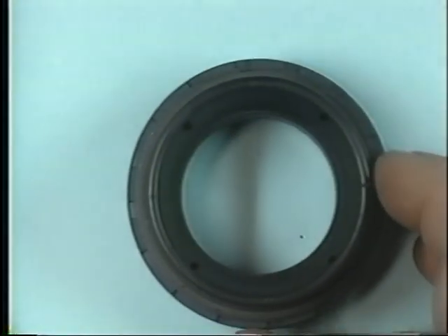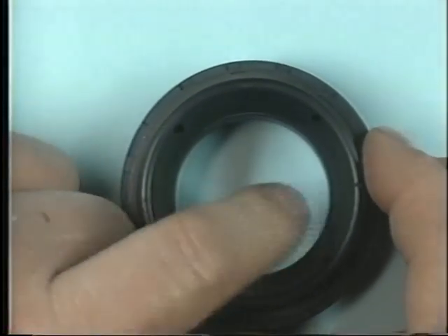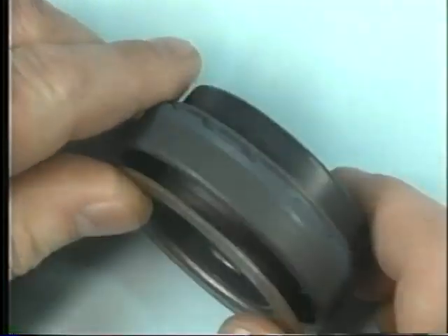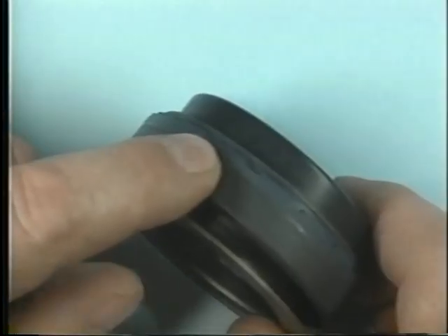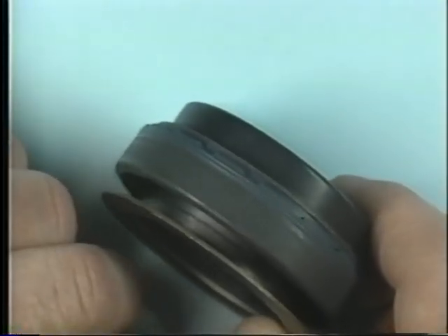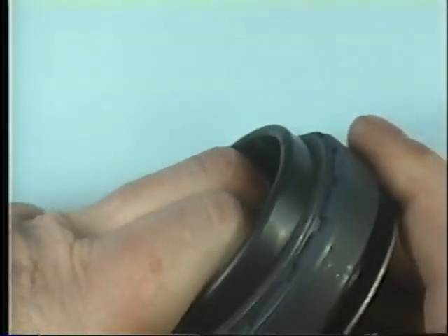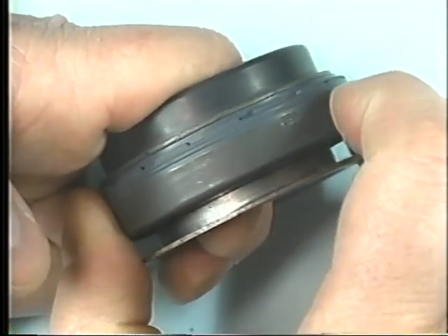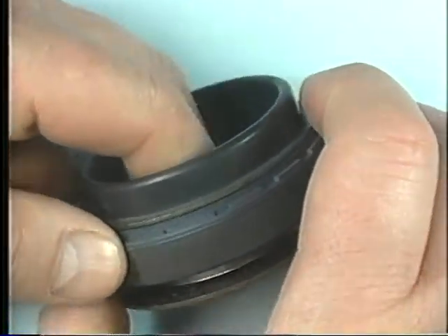So on this particular setup, we're going to have three separate seals here. Obviously, we're going to have a seal on the inside that's going to seal against the axle shaft itself. Another seal on the outer edge seals to the housing. And then, these being two separate pieces, we've got a seal in between the two of them. What that does is it allows this inner portion to turn with the axle shaft. We can turn that. Ours is a little bit stiff because, guess what, it never had any lube on it. The outer portion stays steady, and the inner portion is going to rotate with the axle shaft.